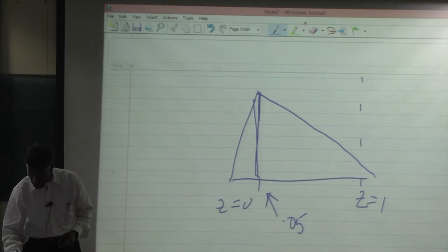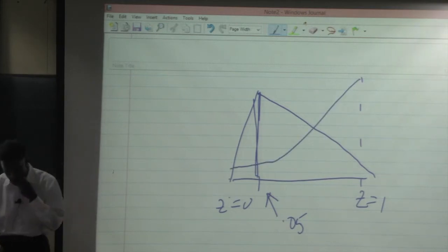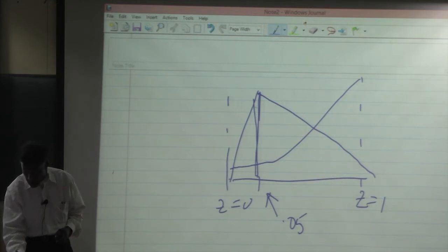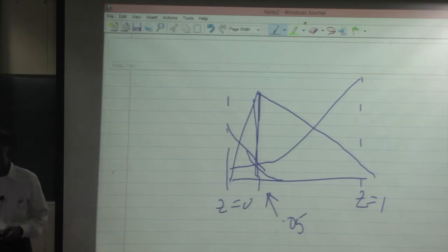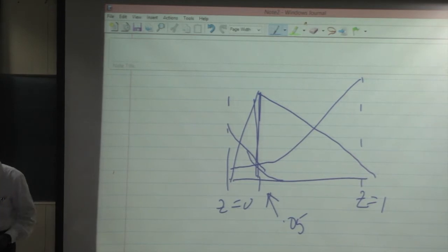If a fuel comes in, because there's a rapid decrease in temperature, the fuel actually leaks through the reaction zone. And since the activation energy is large, it causes the fuel to leak. On the other hand, oxygen does not leak because the gradients of temperature on this side are not as steep. Therefore the oxygen is completely consumed, and the fuel leaks for that reason. Because of the sharp gradient, it quickly freezes the chemical reaction and leads to leakage of fuel.